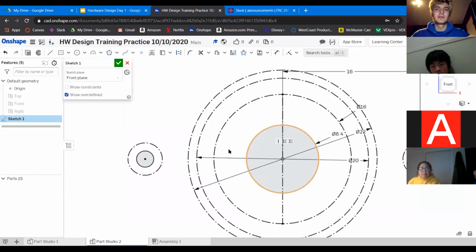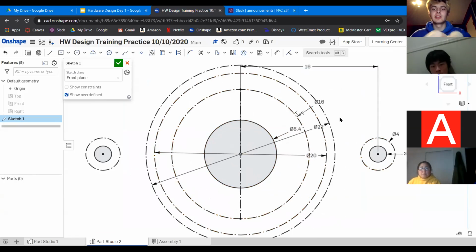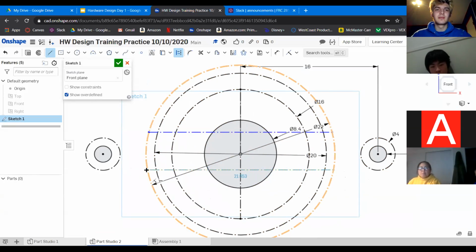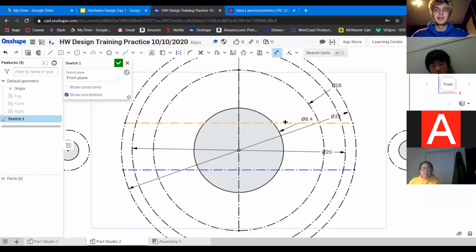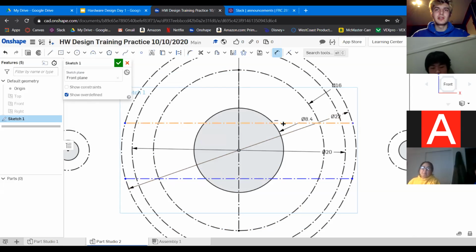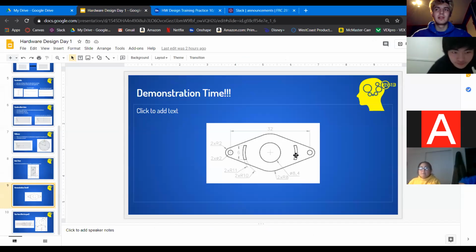So what you're going to want to do is put in lines that start somewhere up here. We'll define them later and make sure it's horizontal because we know that these are horizontal to the origin. These are going to be construction also. Notice that it's also not defined yet. Okay. And did I make this horizontal? I did. Okay. And then we're going to dimension the space between these two to be 6 inches because we know that this spot is 6 inches right here.